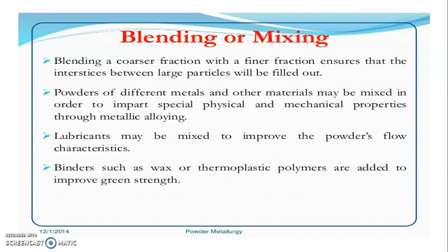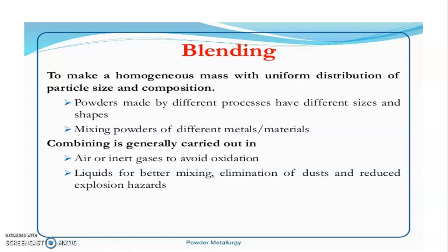Binders such as wax and thermoplastic polymers are added to improve the green strength. Then blending, to make a homogeneous mass with a uniform distribution of particle size and composition. That is a very important point.